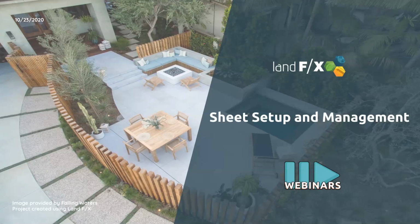Yes, there's a lot of ways to do sheet setup in CAD. I think we all know somebody, or maybe are guilty ourselves, of not even using paper space, just putting a large title block right in model space. It's not best CAD practices. So what we're showing today is what we would definitely prefer, because we don't want to waste our time trying to help someone unwind a mess of a sheet setup that's causing problems with their xrefs or their placing of details. So this webinar is showing best CAD practices for sheet setup.